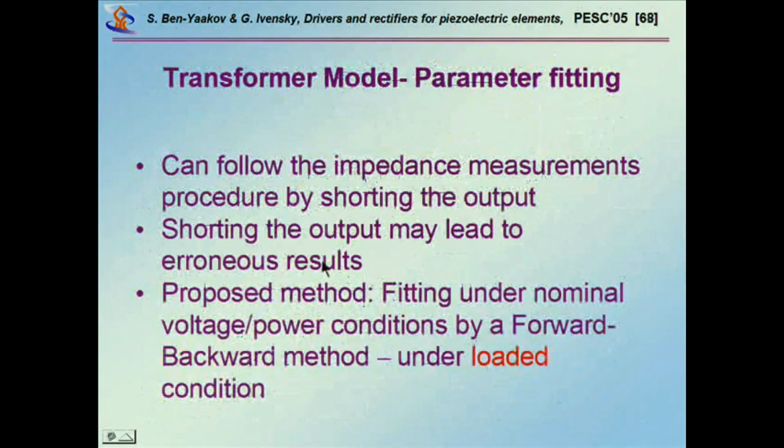Unfortunately, when you short the output, you change the operating point considerably. And we have found that the model that you get is very much different from the model under the real operating point. So this is not a good practice if you need a very fine model. The best thing to do is, again, to do the fitting under the real operating condition.